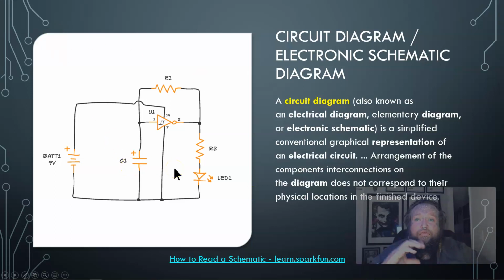And so I'm going to be introducing some of these, and they're good to learn. It's not that bad to remember some of them. You don't need to go super crazy with it. But you get things like the power source showing the positive, and you have the negative side. You know, these lines that are drawn out here are showing the connections. The jump over here means, well, these two lines aren't connected, whereas the dot here means, yeah, these are connected. You get zigzag lines for resistors and things like diodes. And don't worry, I'll go through the components, we have diagrams there, but you just need to know how do I read these?